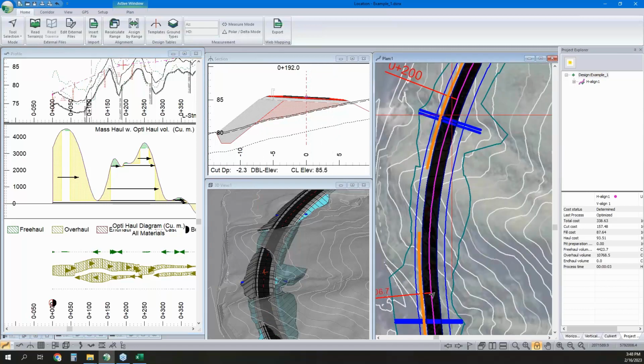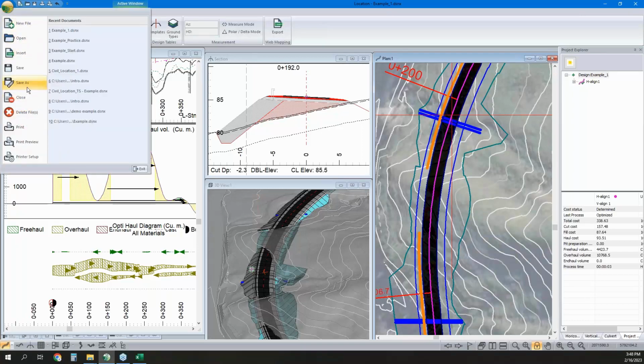If we save it out as a LandXML file, that alignment is a proper curve where we have curves. So rather than sampling in a series of lines connected together, it's a formula representing that curve for us. So LandXML is a nice format. It's meant to be kind of a universal format.